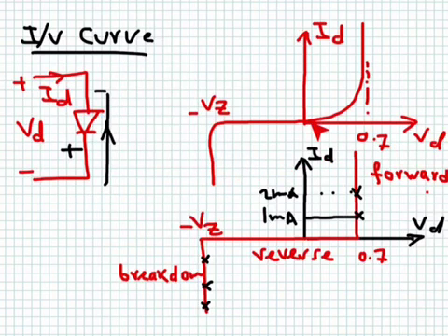Here, when you increase the voltage from 0 to around 0.7, the current is small, and then suddenly it sees an exponential growth around 0.7. We usually ignore this transition. It's a little bit of a sharp transition, and we try to approximate it by this vertical line. The same thing will happen in the other direction.